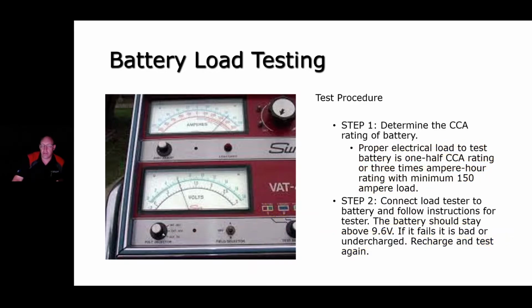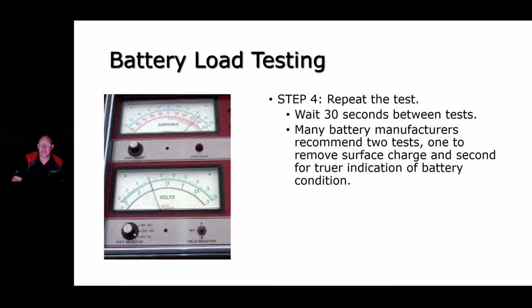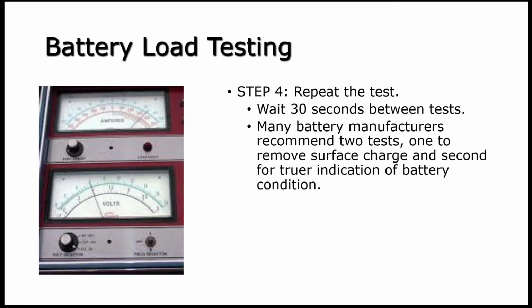All right, moving on. Battery load testing, step 3. Apply the load for a full 15 seconds. Observe the voltmeter during the 15 seconds, and it should stay above 9.6 volts. We've already talked about that, right? Okay, so moving to the next step.